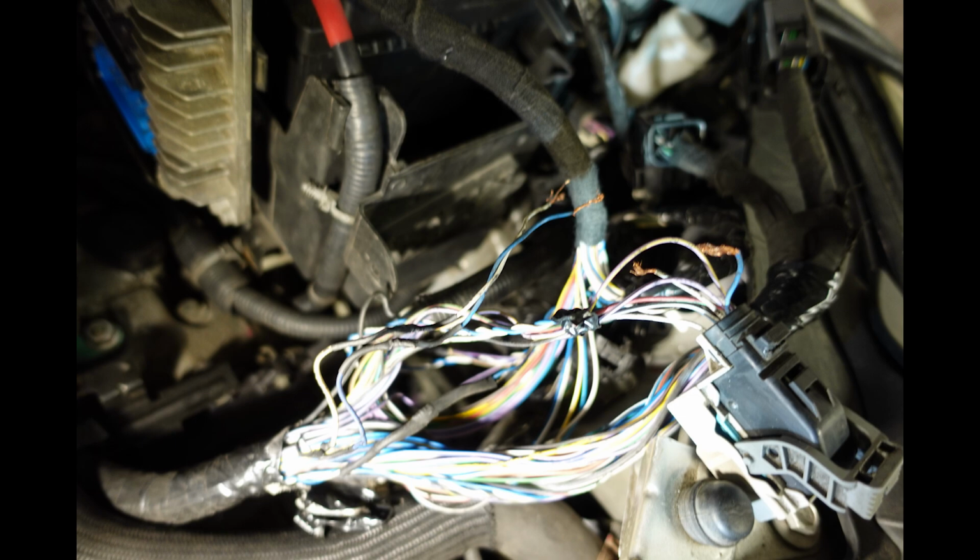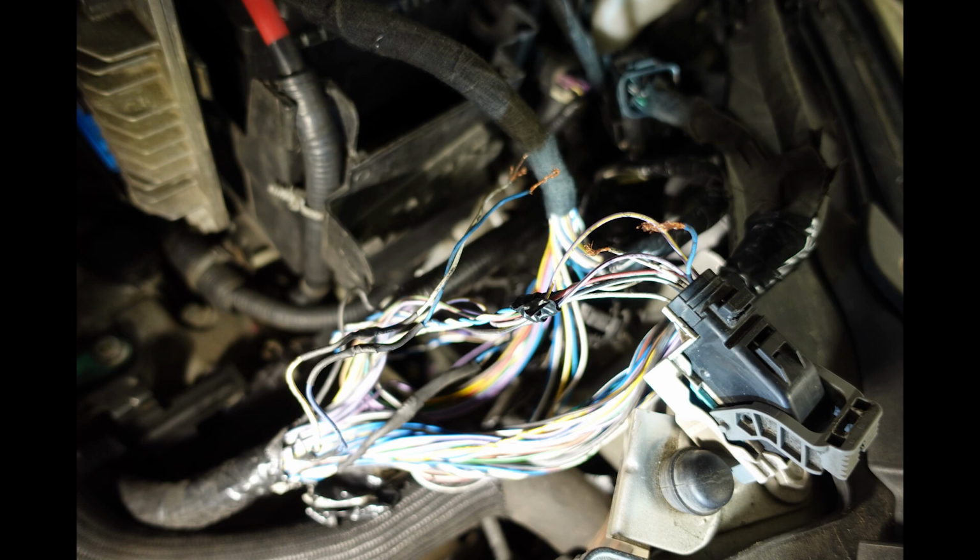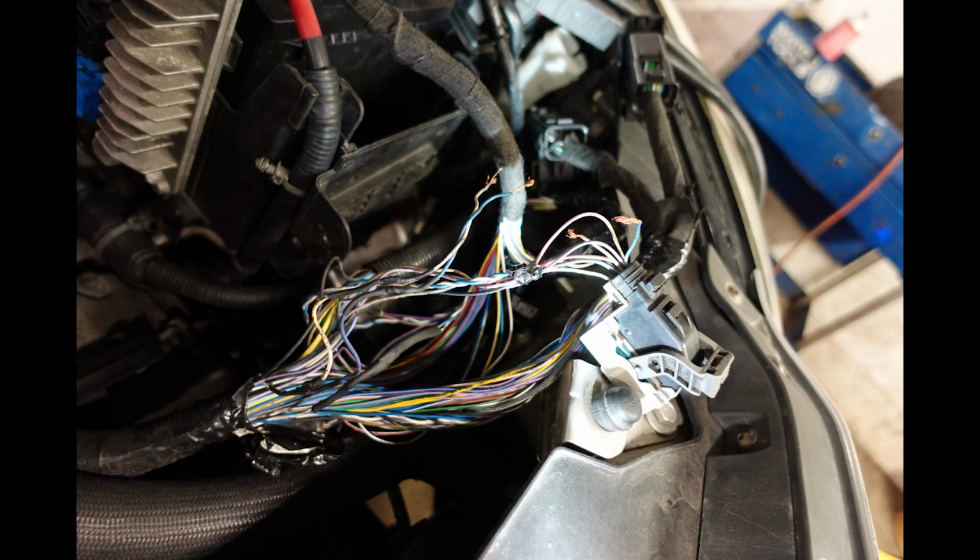They're the best. I'm working on a vehicle right now that's at a shop for a fuel pump control module, a 2013 Chevy Malibu. I'm sorry, I was getting my Fords mixed up with GM. Today I'm working on one, and somebody spliced the CAN bus in multiple spots by the transmission control module, and I think it's connector 115 underneath the hood. All kinds of crazy stuff. No communication with the fuel pump control module. However, I do have a data line signal back there.